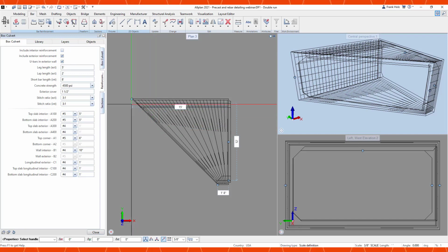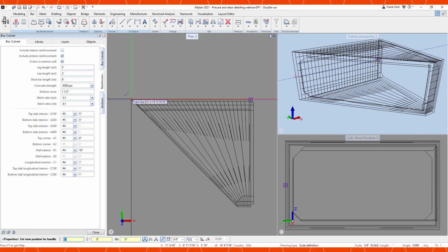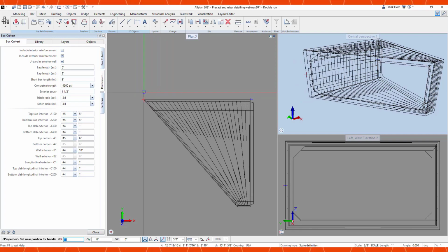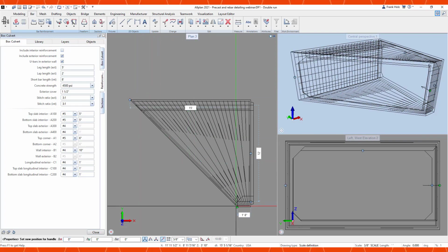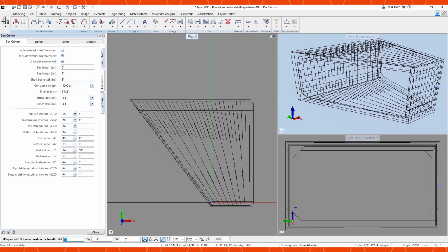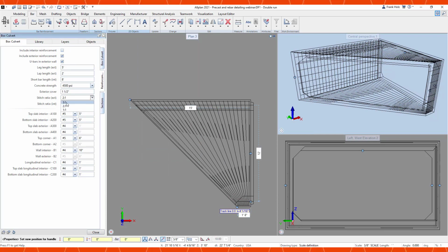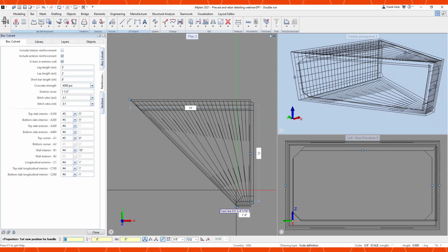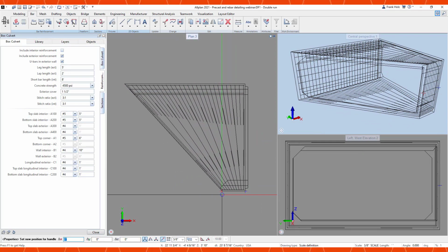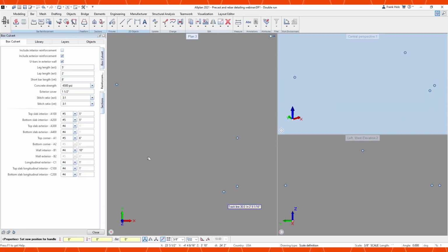For this particular requirement, the customer wanted it so that on the long side we maintained a 6-inch spacing, and so as I get longer or shorter, it's going to add or remove bars as necessary. On the shorter side though, it's going to accordion out, so it's going to maintain that stitch ratio of, in this case, 1:3. I could easily change this as 2:1, 5:4, 4:3. It was whatever the customer wanted, but you can see that it automatically adapts, and it's all rule-based, logic-based, so it's full control, doing exactly what we want.